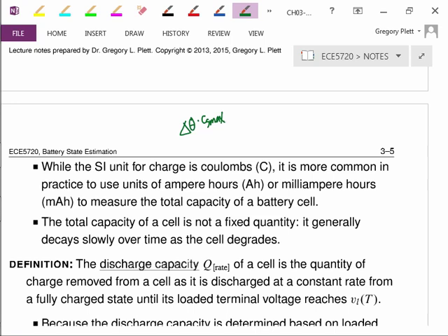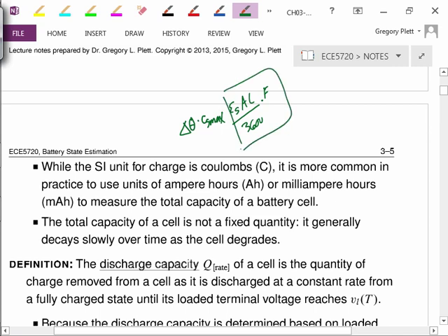That has to be normalized into ampere hours, and we saw how to do it last semester. We have to multiply by epsilon_s α over 3600 times F to get it into ampere hours, but it's proportional to c_s,max. The capacity, if you want to think about what it really means, is how many vacancies there are in the structure of the electrode that I can use to put lithium in or take lithium out of. You think about it, it's just the number of rooms in your hotel. If your electrode is a hotel, how many rooms are there?